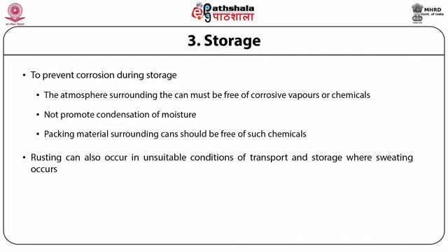This is especially so when cans are transported from temperate to tropical areas, or temperate to temperate areas via the tropical areas. Attempts to prevent condensation of moisture by free movement of air have usually been unsuccessful because the centers of the stacks of cartons filled with cans take a long time to respond to the external temperature change and may remain below the dew point for longer periods.